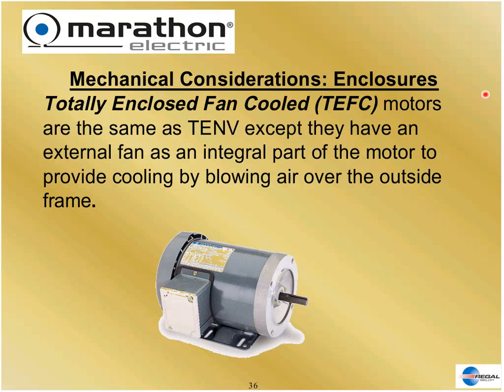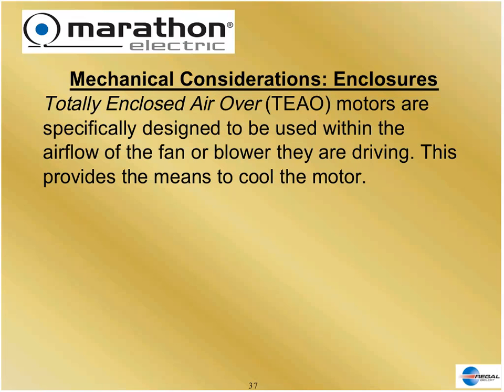On an enclosed motor, the most efficient way is to put the fan that we had inside the previous motor on the outside. Now, at least we can blow air along the case of the motor, the frame of the motor, and try to wick the heat out from the center. We can't get it inside, but we can certainly blow it on the outside, and that will cool the frame and keep the heat from damaging our motor. We can have a totally enclosed air-over motor in which the customer would supply the fan if we were driving a fan, and that fan would supply the air over the motor.